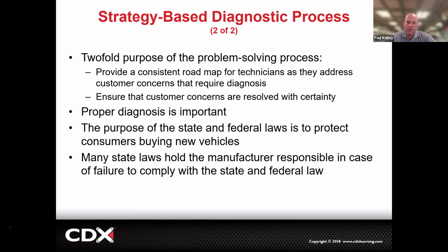It's not good. Right. So ideally, we get the car in, we drive it. It operates normally. You compare it to another known good. You document that it's operating normally. You give it back. Now, if they really want to keep coming back and saying, hey, once in a while, my recommendation would be to kind of put some more of the responsibility on the customer and just say, look, we believe you. We're not calling you a liar, but we can't diagnose this unless it's happening. So if you can't help me make it happen and we can't make it happen, we can't fix it.